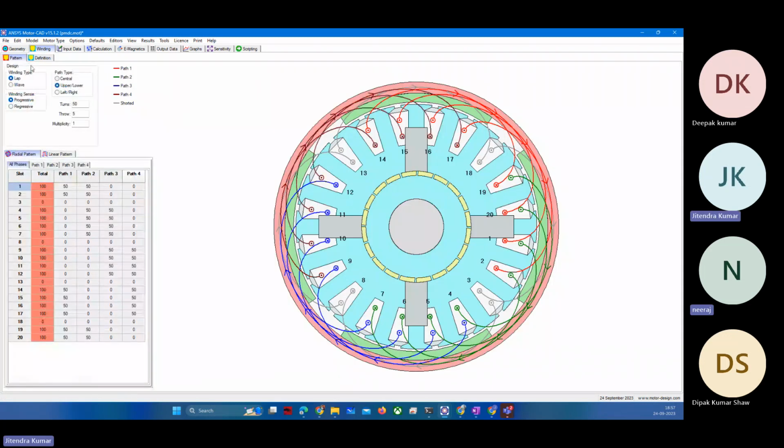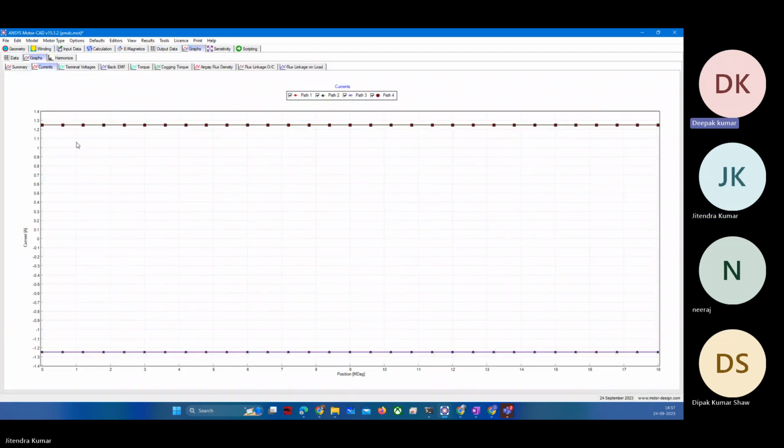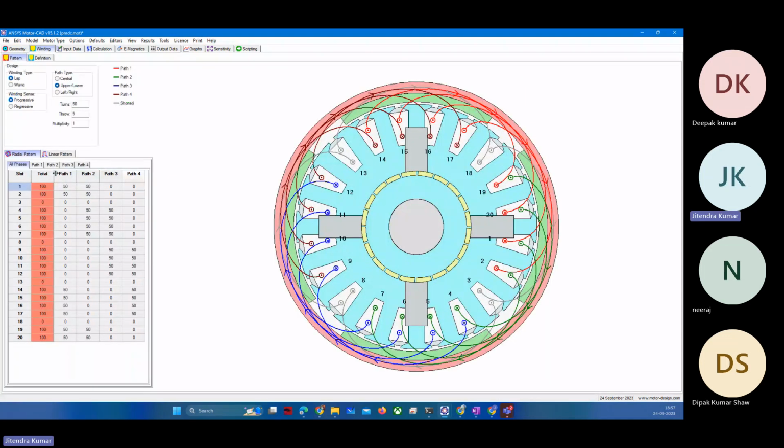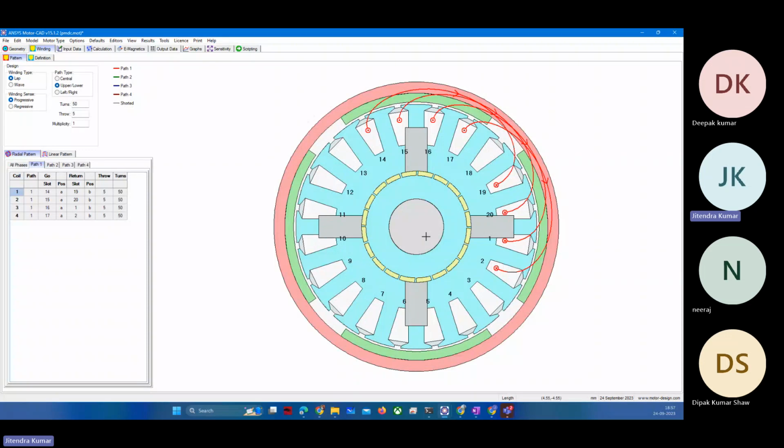Any other question from this section? Sir, the current going into the armature is pulsating AC? The current going into the armature is DC. After the brushes also it is DC. It's just that the distribution of those windings is such that they create magnetic flux that is not DC, that is not constant.